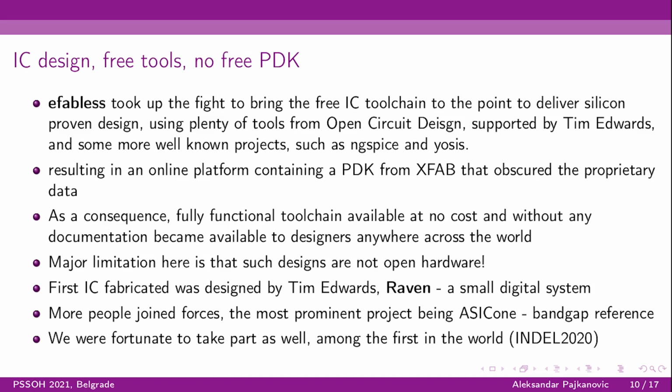So basically, for the last few years, we already have a fully functional toolchain available at no cost, and also without any documentation, apart from honoring the open source license. So we would still have to obtain the PDK under an NDA, and the major limitation here is that such a design would not be open hardware.